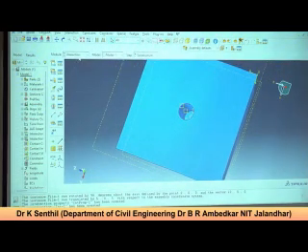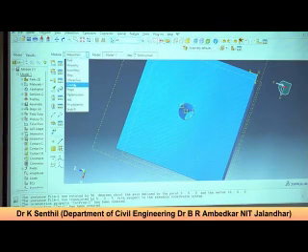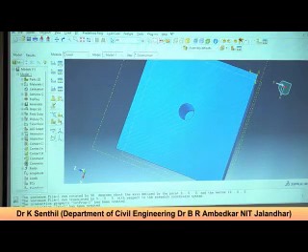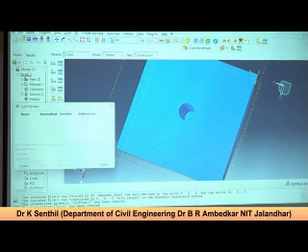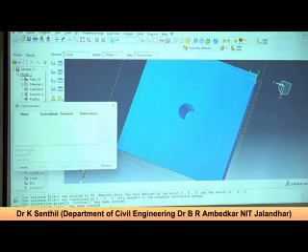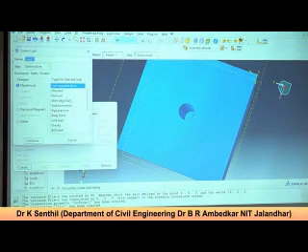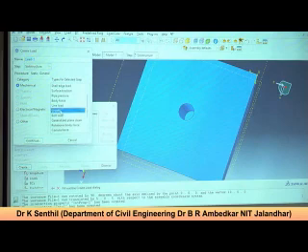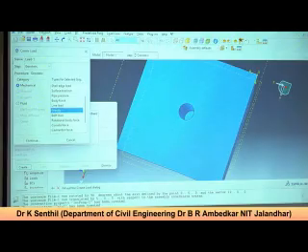Okay, I think the interaction is only this much. That's fine, sufficient. No need to do anything further. Now let's go to the load module. There we'll use the geostatic step because that will be the gravity load. Boundary conditions? Okay, create gravity load. This should be geostatic. Geostatic, then the gravity load.